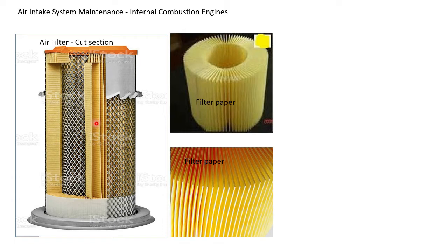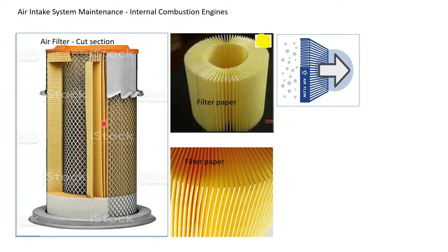That's why you have to be careful. Some people will sell spurious filters. Externally, the size of the filter may look the same as the genuine filter, but when you cut the paper element, the area of the filter will be smaller. The number of pleats in the paper element will be lesser. So it is essential to use only genuine filters.